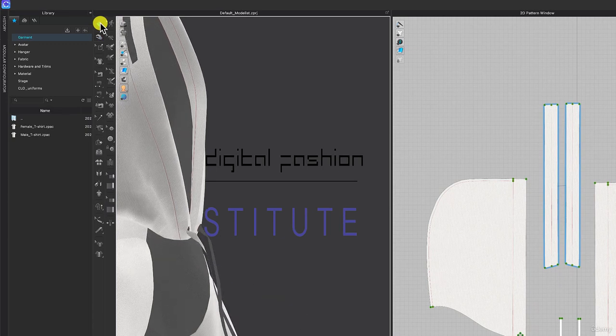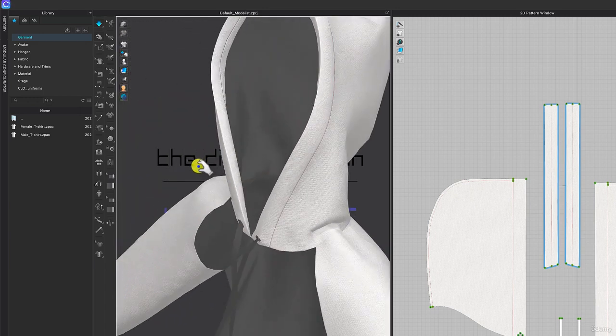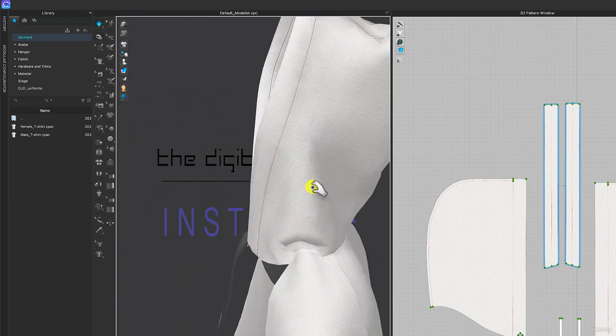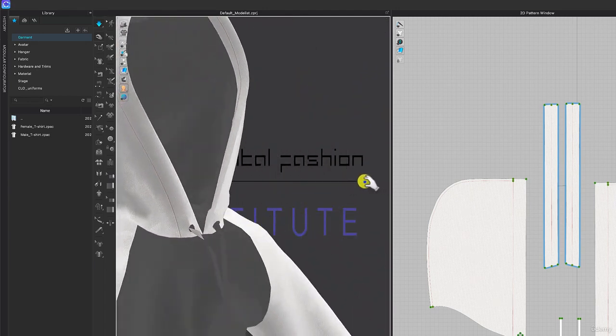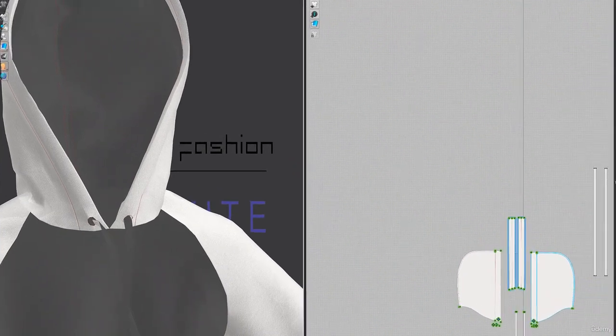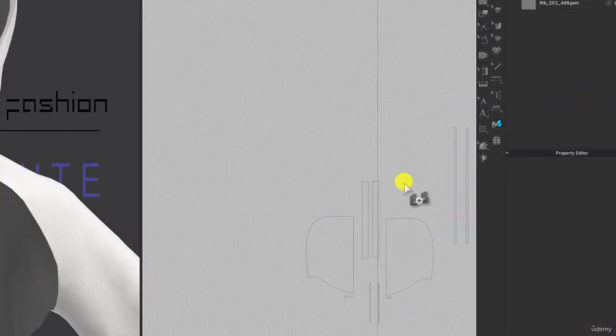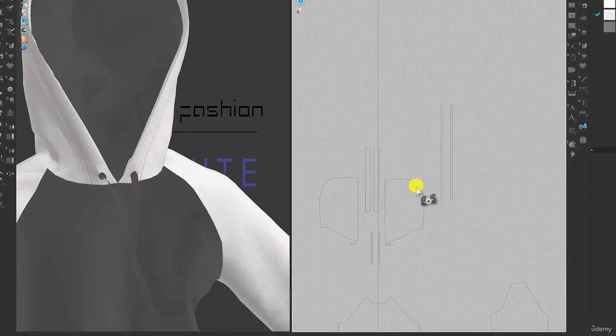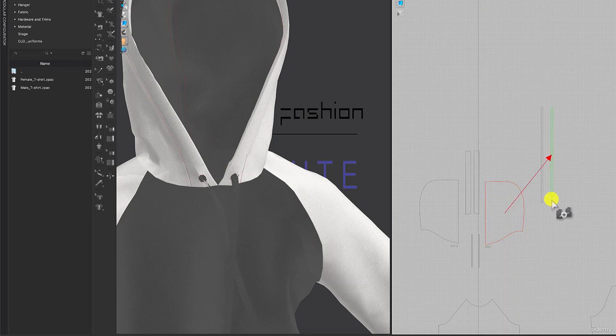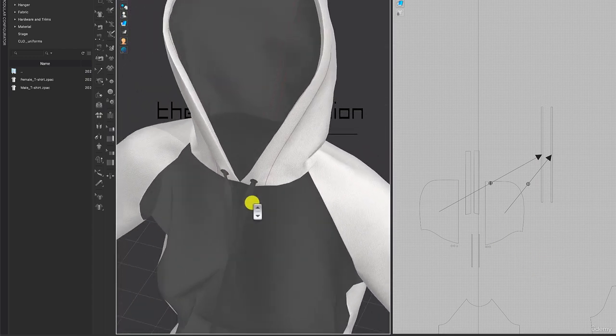If there is a lot of collision, stop the simulation and try this process again. Eventually, it'll come together. Sometimes when there is collision, you can fix the issue by setting your sublayer using the Set Sublayer tool. With the tool selected, click on the hood pattern piece in your 2D window, then on the drawstring. Most issues with collision will automatically resolve.